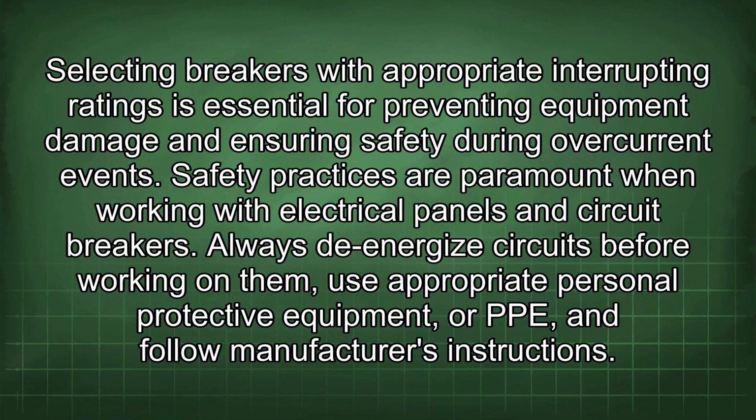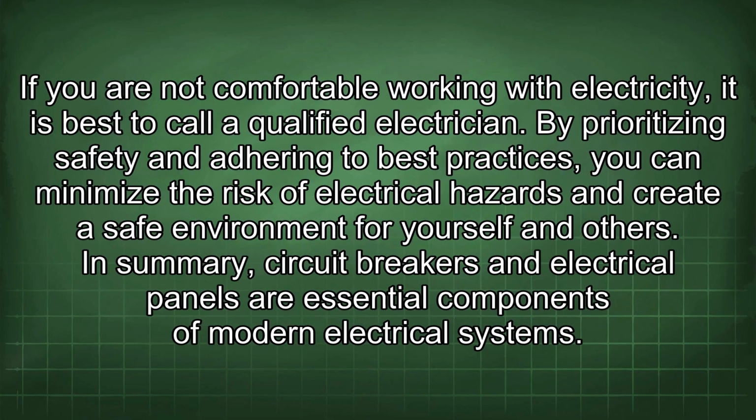Always de-energize circuits before working on them, use appropriate personal protective equipment, or PPE, and follow manufacturer's instructions. If you are not comfortable working with electricity, it is best to call a qualified electrician. By prioritizing safety and adhering to best practices, you can minimize the risk of electrical hazards and create a safe environment for yourself and others.